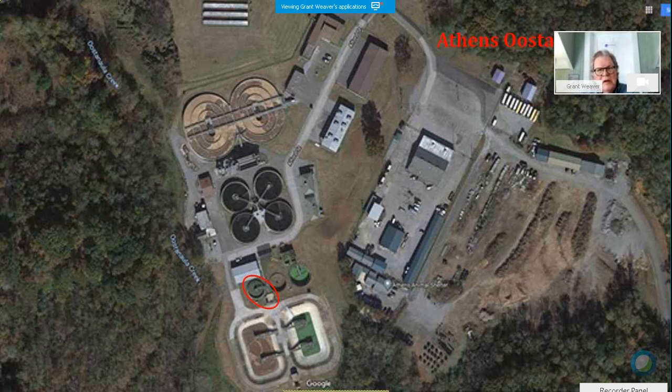And as it fermented, create volatile fatty acids. As the volatile fatty acids were created, the waste or RAS that went into that would consume the volatile fatty acids. They become energized, and then through that pumping station would be sent back into the orbital ditch.